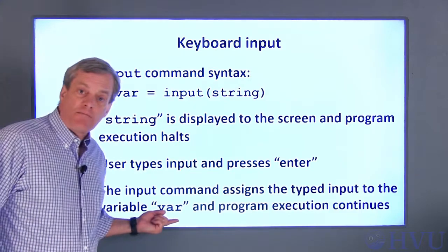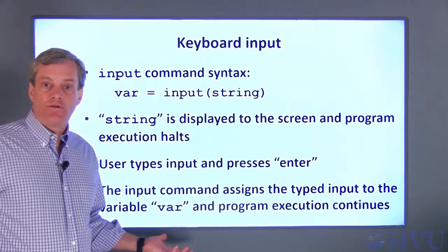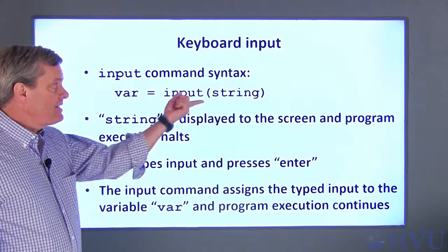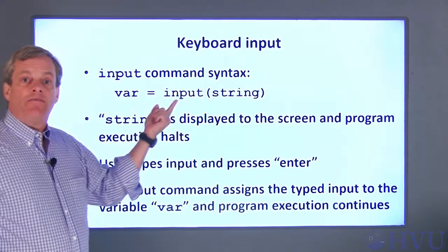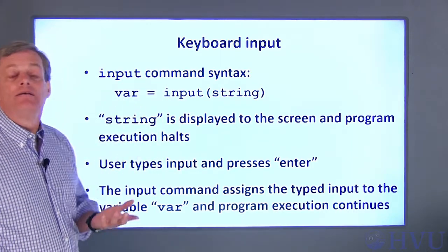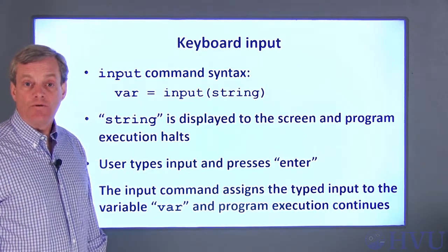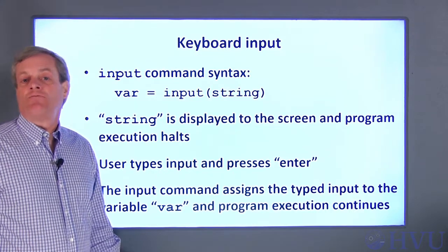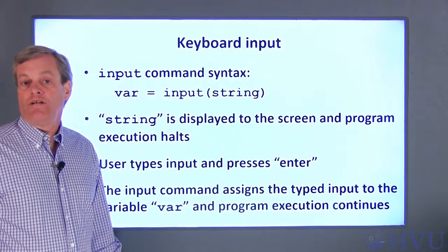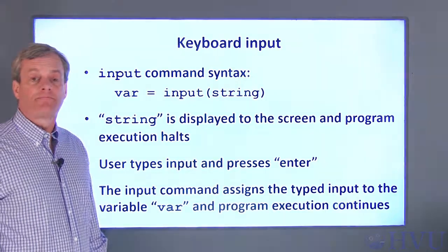Once the enter key is pressed, MATLAB's input command reads the information the user typed. In this syntax above, this result is assigned to a variable named var. Now var is a defined variable and the program's execution continues. I'll use the script file from the second Chapter 4 video, which calculates beam deflection, to illustrate how this works.